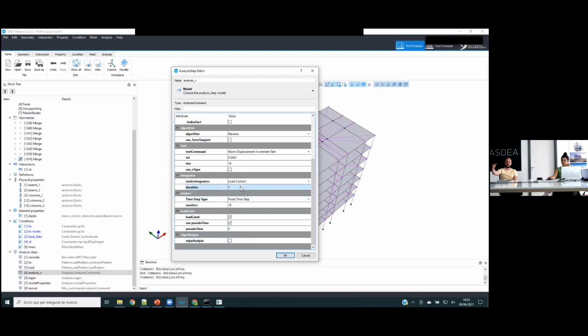If you do another analysis, going to time 2, your reference loads will not stay constant. They will keep on increasing, okay, because your time is increasing. So one way to tell OpenSees to keep some loads constant is to use this command. The load constant basically says that all the loads defined before this command will not depend anymore on their time series, but they will be kept constant in the subsequent analysis. Okay, this is very useful when you do, for example, pushover. So you do gravity analysis, you increase your vertical loads from 0 to 100%, and then you keep them constant.